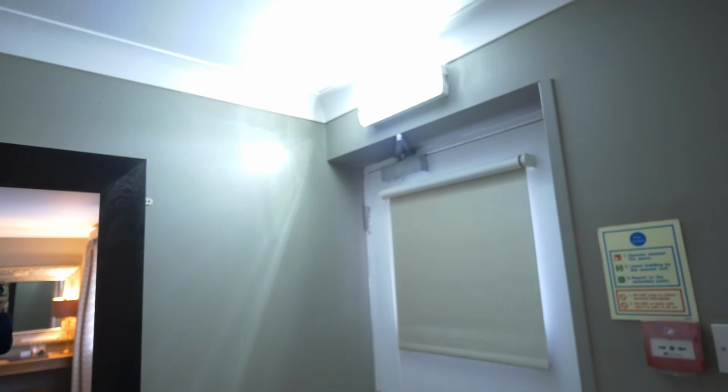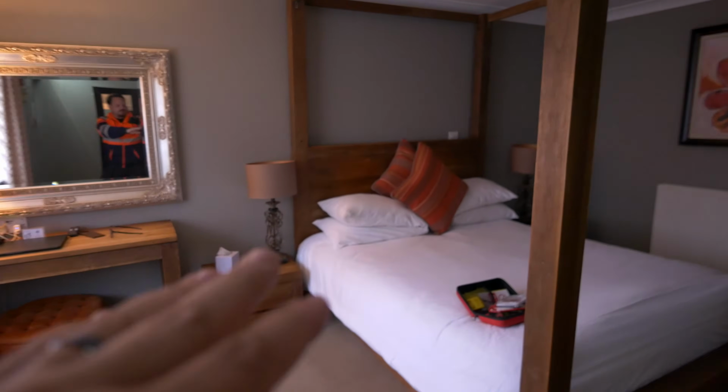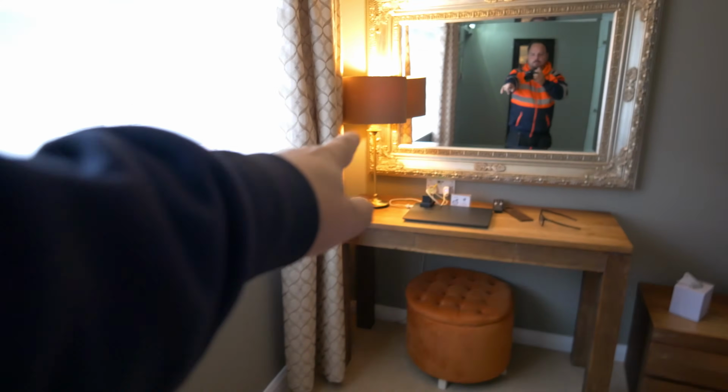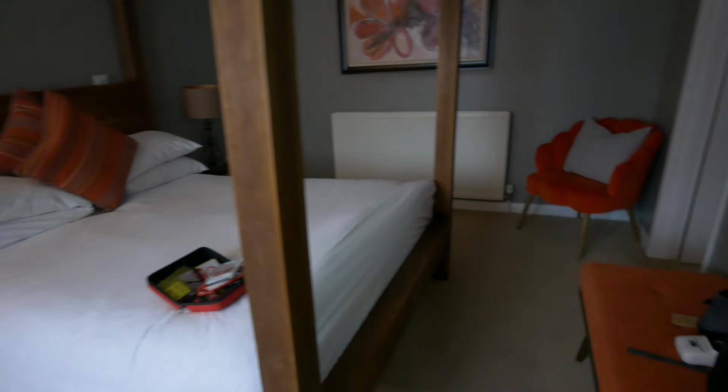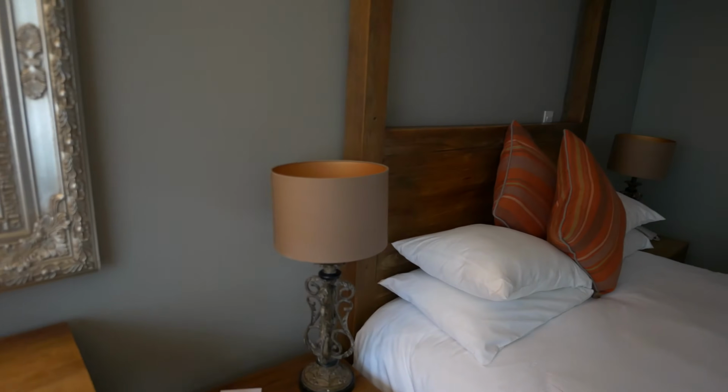We've popped the power off on what I suspect to be the lighting circuit. We can see that emergency light's activated, so that's seeing that. We can see this has gone off. The bedside lamps have gone off. This lamp that's plugged into the socket outlet has remained on, which is useful. We've lost all the power in the bathroom. Lamps are off, lights off, fans off. So that's a good indicator to us that all of the lighting points, including those 6 amp outlets just down behind the bed, are all wired off the lighting circuit. So happy days. Can pop the power back on for the moment.